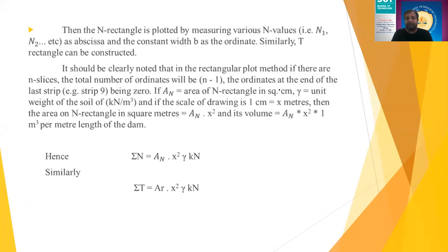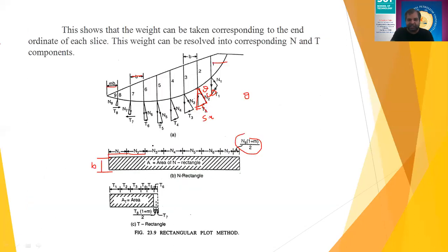But you need to remember, if the direction changes, as you see, all these are going in a leftward side, you can take plus. Then when a slice goes in the positive direction, you need to take the minus while finding the sine component of this.